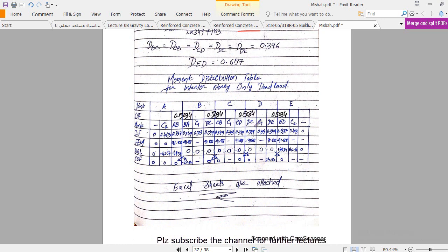Now this is the table which I drew here. You see joints, you see carryover factor, which we already determined from table F14 in lecture number 4. At the joint of AB we will use this carryover factor. At BC, although in our undergrad courses we use carryover factor half, 0.5, here you see that this one will be different. Similarly at BC for CD, the spans are the same, that's why the carryover factor is the same. If the spans are different with a different geometry, then these carryover factors will be different.